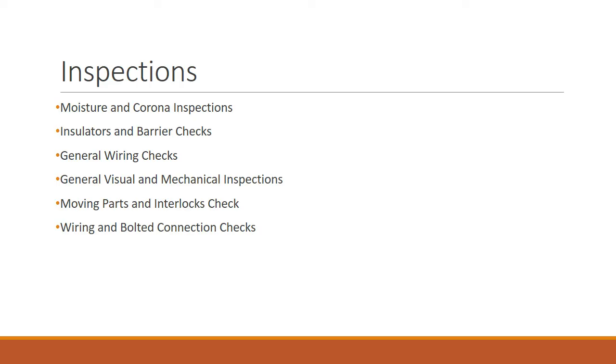When completing maintenance checks, you should look for signs of moisture or corona. Roof or wall seams should be examined for indications of leakage on exterior components, and any leaking seams should be sealed with weatherproof caulk. You should also check for correct operation of all interior and outside lighting. In the event of an emergency response or for other security concerns, it is critical that the area where the switchgear is situated is properly illuminated at all times.